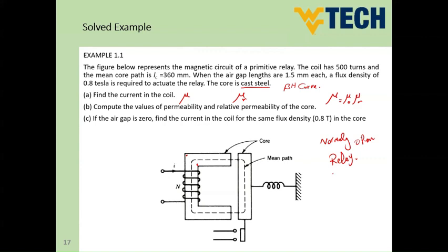Okay. So this means, guys, if the relay is open, no energization, the required current at the start would be 4.19 ampere. And the current will be just 0.3 ampere if the I shape is attracted to the C shape.